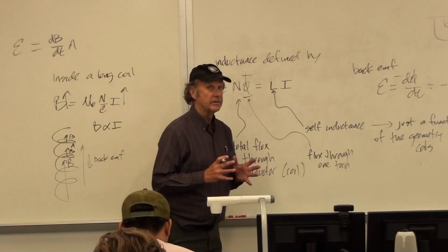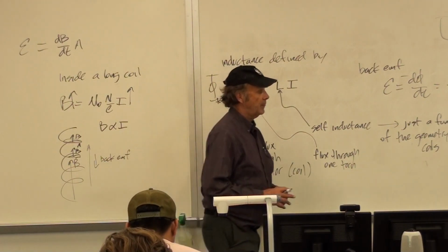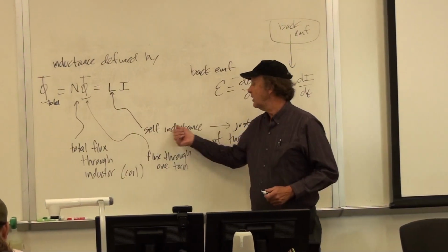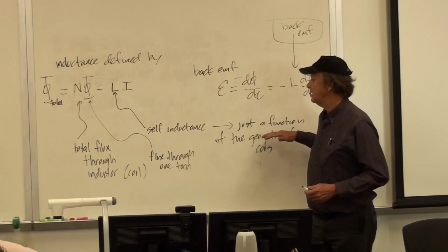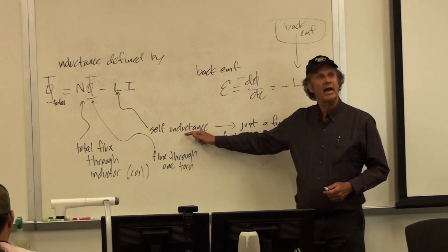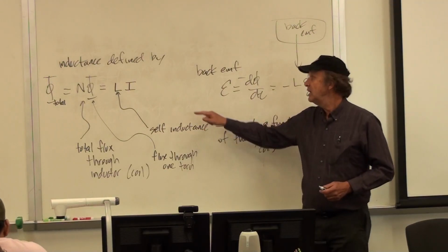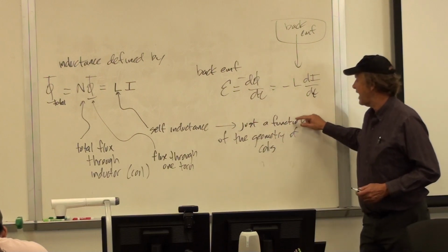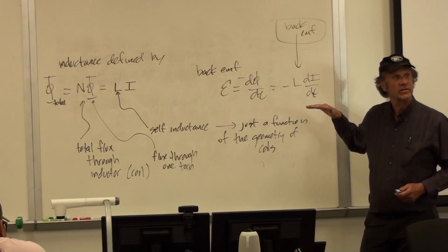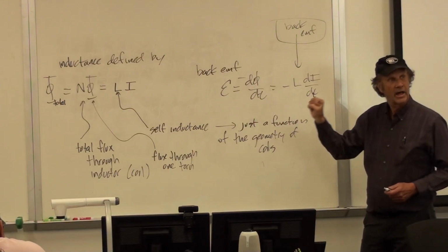We talk about electromechanical analogies, and in a mass system, the energy is 1/2 mv squared. What we're going to show is that in a current-carrying inductor, the energy is 1/2 L I squared. And so there's an electromechanical analogy between the self-inductance because it acts like an inertia term that fights against the changes that produced it, just like inertia fights against changes in velocity.